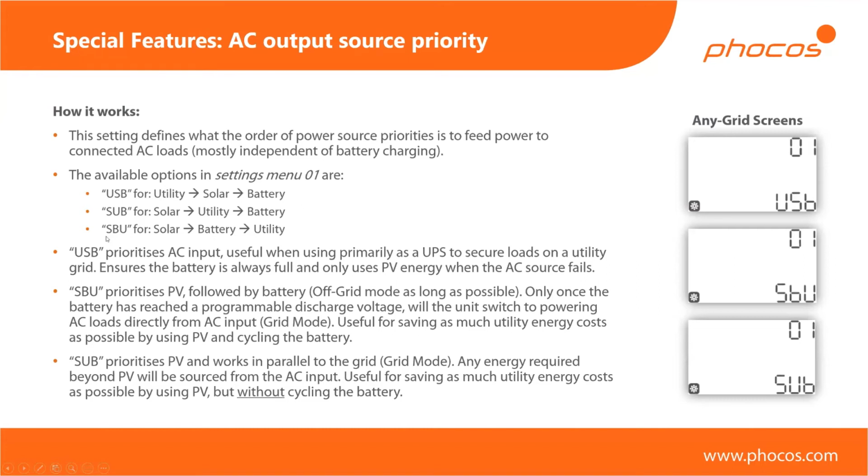Because of course, if you're allowing the system to discharge your battery even when the grid is there, well, that means you can discharge your battery by say 50% during the night and then recharge during the day, and of course use solar power on the fly as well. And that just means that overall, throughout the year, you're going to be using a lot more solar power, even with the exact same solar array, simply because you're using the battery for buffering as well. And you can still freely choose how deeply you want to discharge your battery every day in your cycles so that you still have a certain power reserve for when the grid does fail.